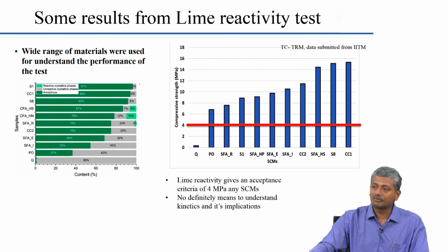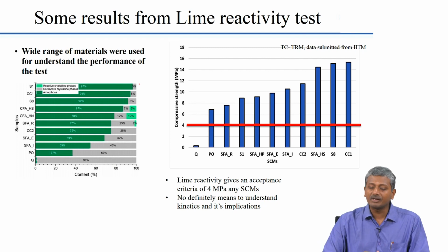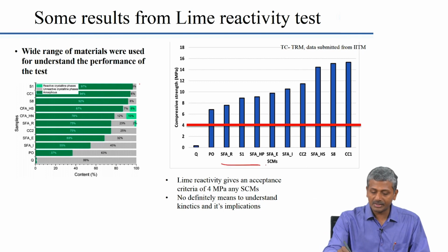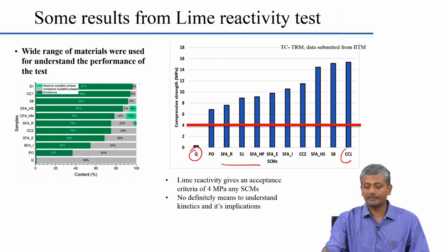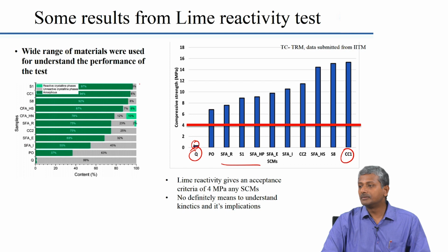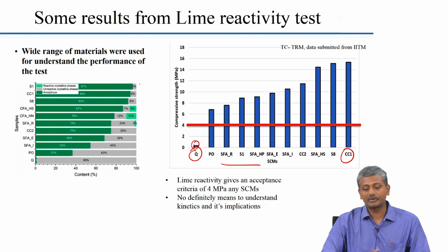So, this is again part of a large group of laboratories that are involved around the world in doing round robin testing of several different types of mineral additives, slags, fly ashes, type F, type C fly ashes, quartz, calcined clay, several different types of systems are being used in this case. So, here you can see that when you use quartz, nothing is happening. Why? Because there is no reaction at all. Quartz is not reacting with calcium hydroxide, you do not expect any major strength development at all.